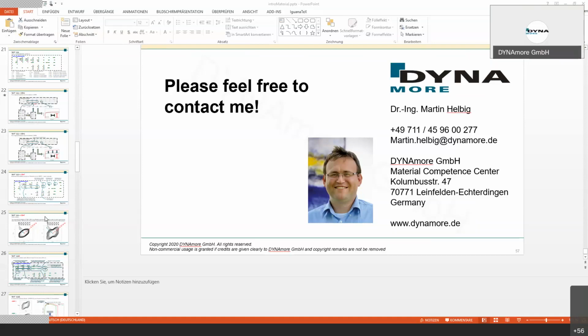Okay, and the last one: you mentioned that MAT_ELASTIC should never be used, and MAT_PLASTIC_KINEMATIC is recommended. In case you see strains are low and well within the elastic range, is there any disadvantage to still using the material card? No. If your model works fine, you will not have any problems. But for larger models, it is useful to use the other one, this MAT_FREE, to avoid these high stresses if you have any numerical problems sometimes. This can happen, especially if an element fails. You can get just a very high deformation at one point, and then you get a very high stress, and sometimes this causes some numerical problems. This can happen, and to avoid this, you can use this MAT_FREE. This was the idea I wanted to convey.